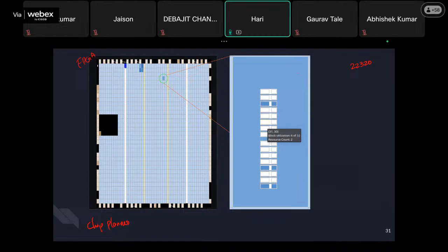And if you can see, there are some gray shaded areas, right? This means this much amount of logic elements I'm using, like this particular block I'm using. These are small blocks, squares and rectangles, right? Within this particular block there are totally 16 configurable logic blocks. Each small rectangle will have 16 logic blocks, but you may or may not use that much amount of logic elements. So if you can see here, I am using 1, 2, and 3 logic elements.